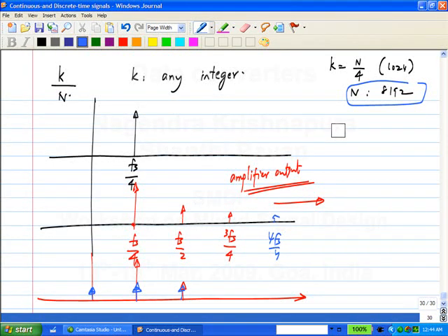What is the fix? Let's say this is fixed. You are still taking an 8192 point DFT sampled at 100 nanoseconds. What is the thing you can fix here? Value of k. Yeah.